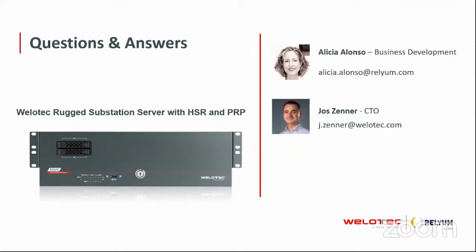Okay. He would also like to know if the HSR packets are moving like tokens. I'm not sure what it means, moving like tokens. Me neither, unfortunately. Well, the thing is that it's transmitted, it switches from one node in the ring till the destination. So there are two duplicated frames, one on one side of the ring, the other one on the other side, and they are not discarded until they reach the destination. The first one is accepted and the second one is discarded.